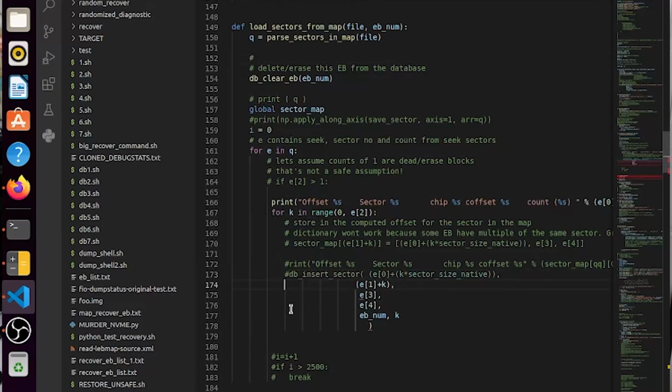You see in the way that one that failed was formatted, it was formatted with 512 byte sectors. Now you could format it as 4K sectors, but again, 10 years old, bleeding edge, they wanted to support everything. So it could show up as a 512 byte device in hardware if you wanted it to, and that happened to be how this was actually set up. But in the NAND dump, 520 bytes. The first 4 bytes is a header, 9000 00, and then the next 4 bytes is the logical block address. And so, hey, write a program, find all the data packets, skip everything else, and start to reassemble things.